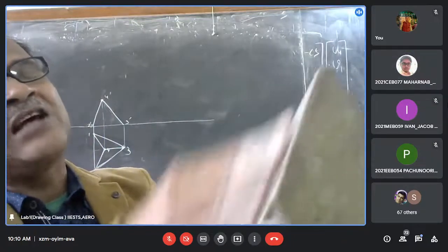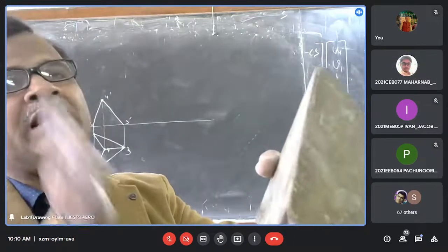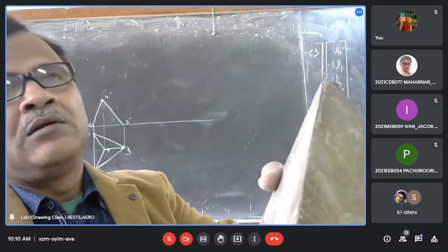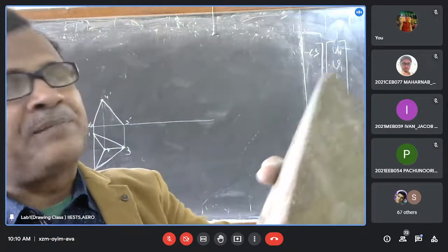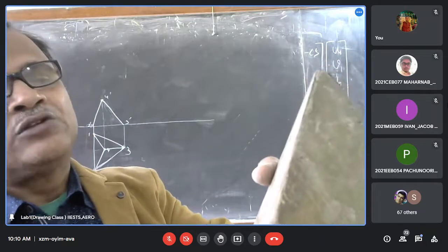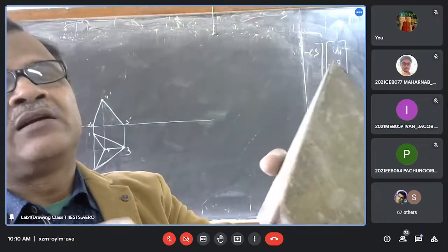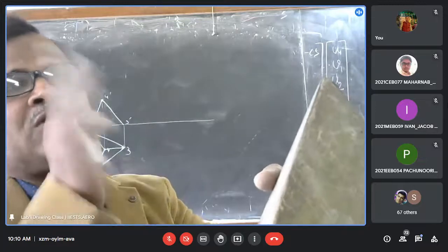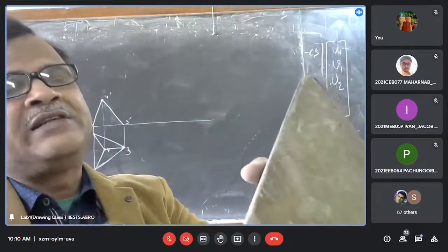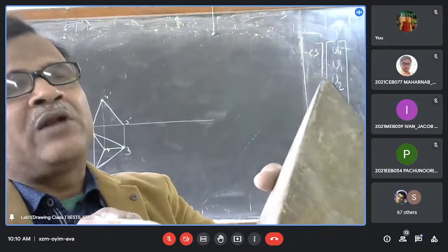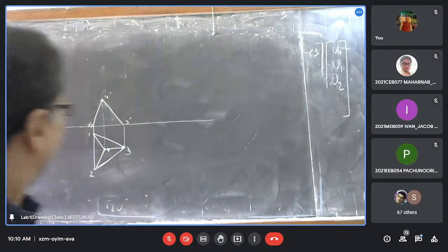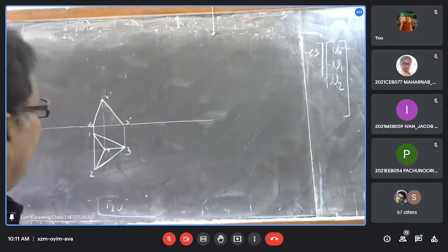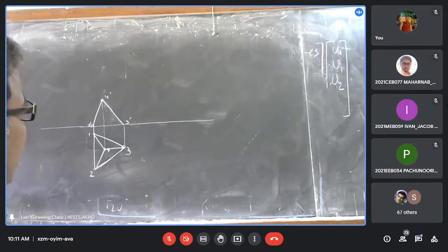While you are giving some angle with the vertical plane to that triangular surface, you should initially make that surface perpendicular to both the planes. Then you make the rotation. Initially you should make that triangular surface or that other rectangular surface perpendicular to both planes. Then give the rotation. Okay. So now if we consider the 1, 2, 4 triangular face.